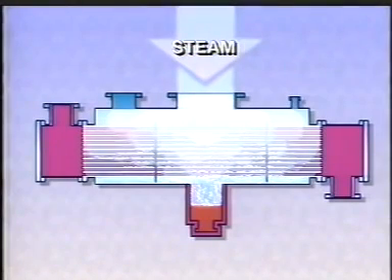When the steam is cooled, it condenses to water and falls into the hot well at the bottom of the condenser. Air also may be used to cool steam. Here, a fan blows air across tubes that carry steam. Although not as efficient as water, the air absorbs heat from the steam and the steam condenses. An air-cooled system may be used if water is scarce.